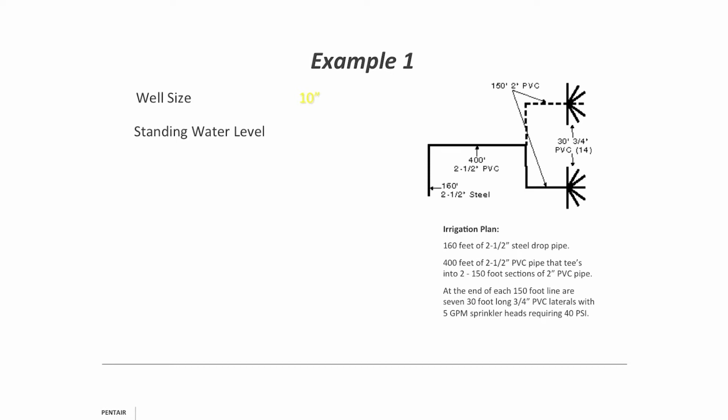Standing water level, he tells me it's 70 feet. And the drawdown, when I ask him, he says it's 60 feet. I asked him, what's the gallon per minute production on that well? He says, it's well over 120 gallons per minute. Here's a point of discussion. Once we determine our gallon per minute requirement, do we do any magical math to play with the number to figure out where the drawdown might be at that point?